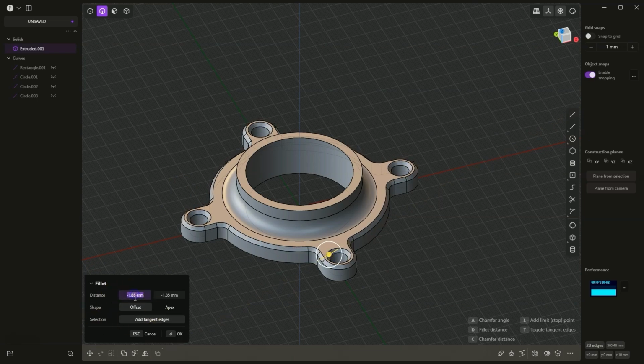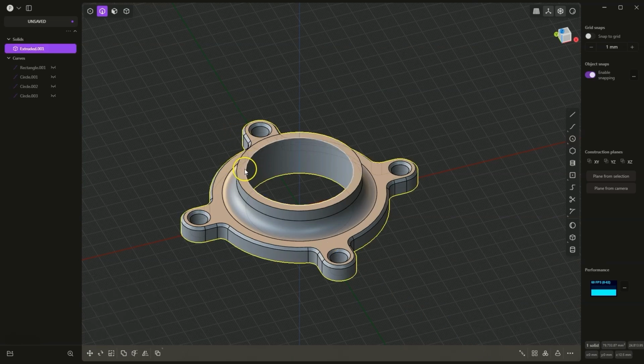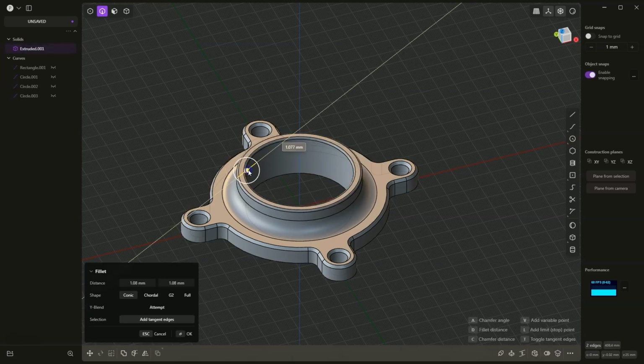And here we add a chamfer of -1.5. We do the same, -1.5. Because if we do something like we did with the radius, which is to add a chamfer of any size and press D and enter some value, the chamfer will be converted to a fillet. If you would like to specify the chamfer size in this way, you should use the C key on the keyboard. We press the C key and now we can enter a specific chamfer value. OK, I press enter to confirm, and we add another chamfer to these edges. I select these two edges with the Shift key and here hit C, 1, enter.